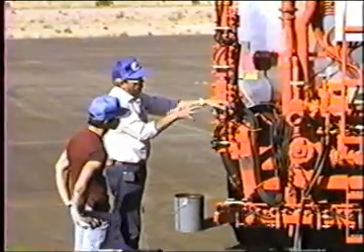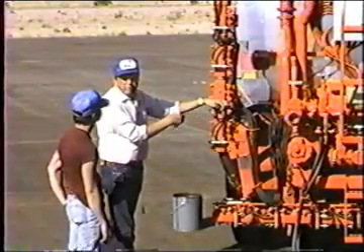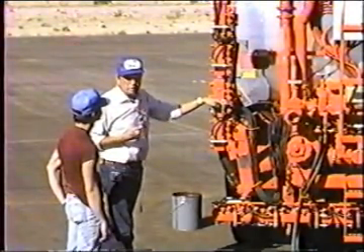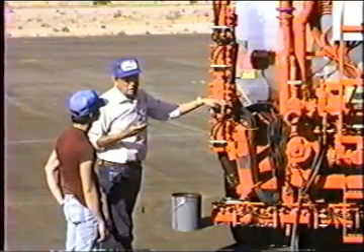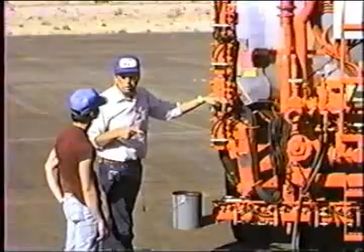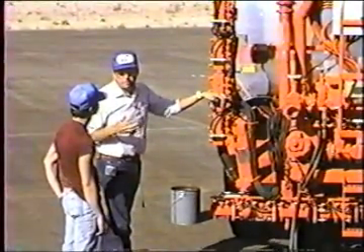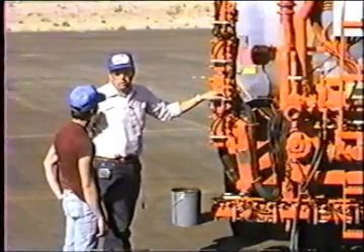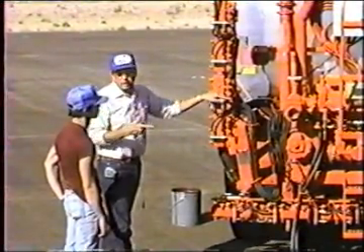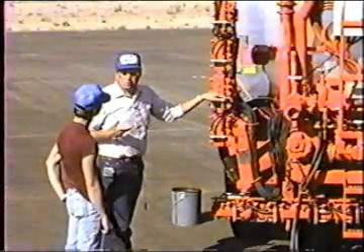The majority of the work that this truck will do in its whole lifetime will be in the range from 5/100ths up through 5/10ths in 1/100th gallon increments. That is, you may get to a job and the man might say, put down 33/100ths of a gallon to the square yard, 0.33. He might say, put down 0.27. If you're in Idaho or if you're in Utah, it's very common for the county guy to come out and say, put down 1/4. Well, that's 0.25. That's 1/4 of a gallon to the square yard.